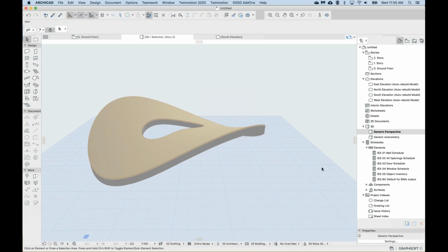Can the spline create a hole for wall and slab? Not for a wall, because you can only create holes in walls with the opening tool or the doors and windows. But in a slab, yes, you can create any shape of hole, and you can use a spline with the magic wand to create that shape. So this hole and contour are actually sub-elements.